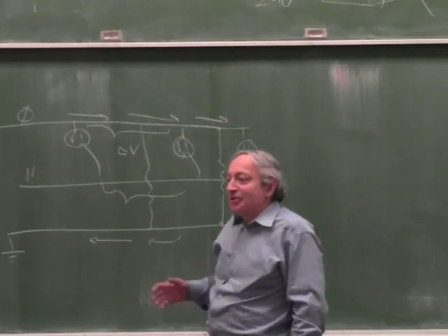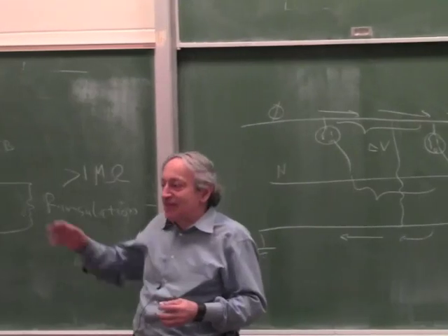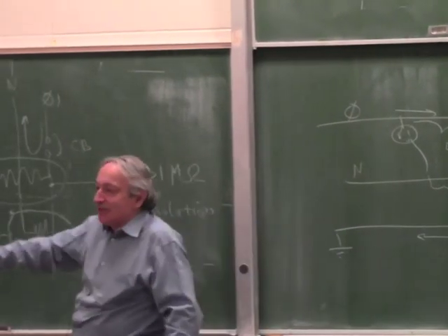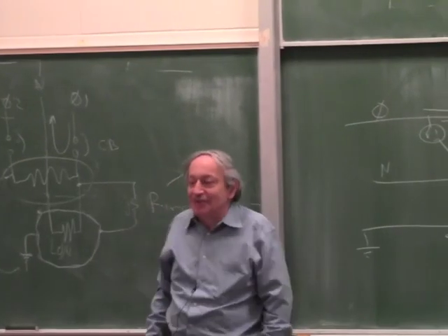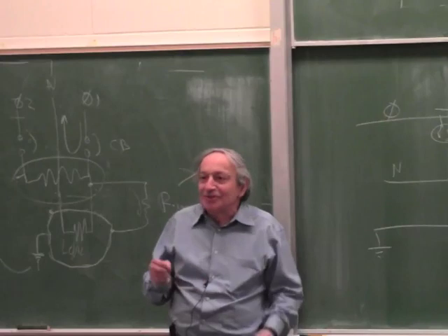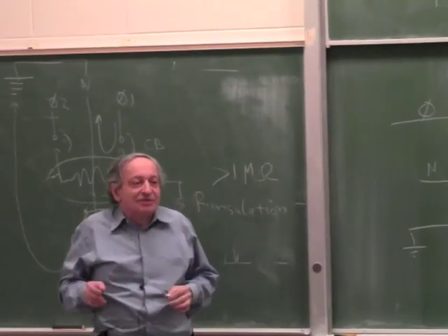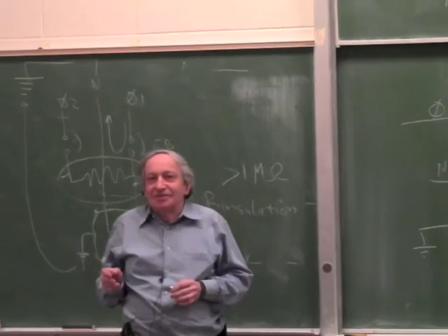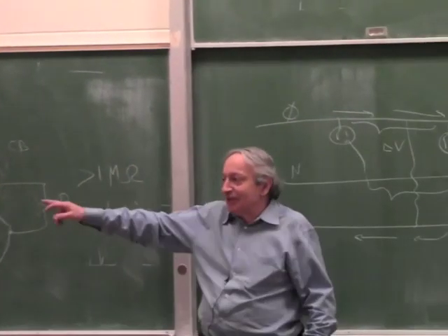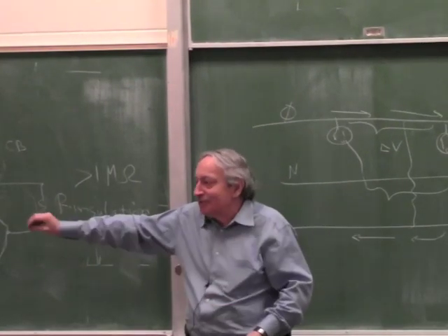So that means when you ground things, you have to be a bit careful, because you have a sensor and a computer at two ends of the room. Sensor is grounded to this outlet, computer is grounded to that outlet. You can actually have some currents through the ground. So ground is not truly 0 volt. And that is the reason why in very sensitive systems, sometimes you don't want to ground different parts to different grounds. You want to bring all the grounds together and then take one wire to ground.